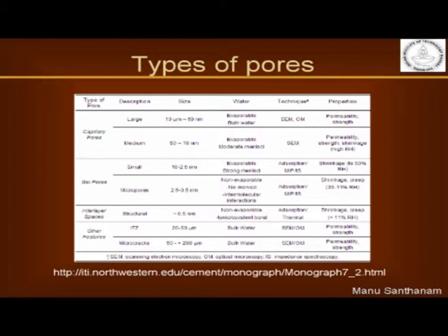What remains stable inside the cementitious system governs how well cement or concrete responds to its environment. CSH, again, as I said earlier, is the primary binding component. It's responsible for strength development of your concrete, but CSH is also responsible for creep and shrinkage inside the concrete. So you have to understand the nature of CSH, the characteristics of CSH, and how you can actually produce concrete which has well controlled properties as far as not just strength and durability are concerned, but also dimensional stability is concerned. And all these factors are actually affected by cement chemistry.